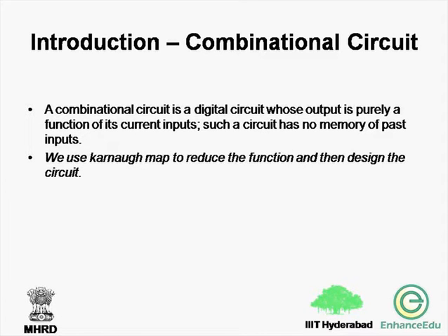The first step in design is to describe the problem, that is, the problem description. In this, the description of the output in terms of the input needs to be done. The second step is to translate that description to a truth table. A truth table is nothing but all possible combinations of the input values written on the left and the desired output values written on the right. Later, go ahead with the derivation of the output equation for each output variable.